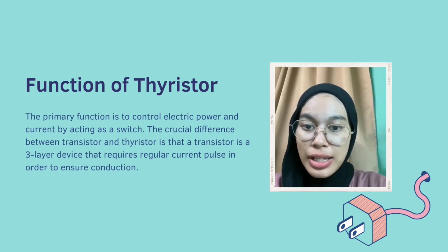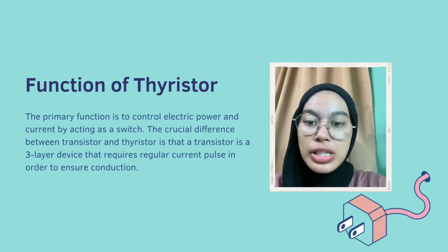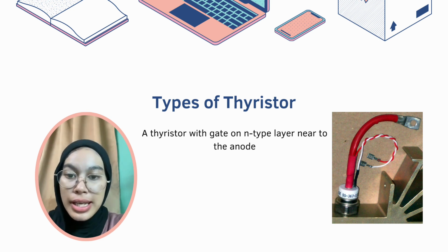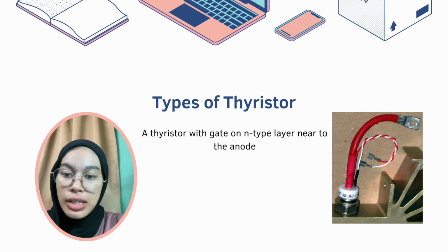Let's take a minute to highlight the unique properties thyristors bring to a circuit by going further into the nature of the signal. The common thyristor solution used in higher current AC switching is 2 isolated SCRs. The added hardware and packaging required to provide the needed isolated heat sinking in this configuration is a cost drawback. Triacs allow a single heatsink but are limited by their thermal performance in current, blocking voltage, and higher frequency applications.